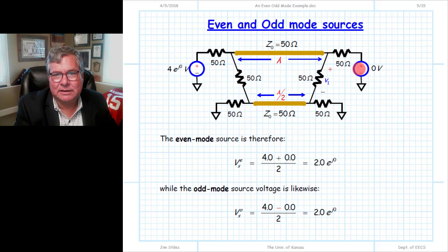And this is a mistake that students sometimes make in this process: they'll put another source down here, for example. But of course, the plane of bilateral symmetry doesn't run through the circuit in this way. It runs in this way. Or sometimes students will put a source here and here and here and here. But again, we just had one original source, reflected across the plane to see where it lands. And that's the place where we need to replace a conductor with a 0-valued voltage source.